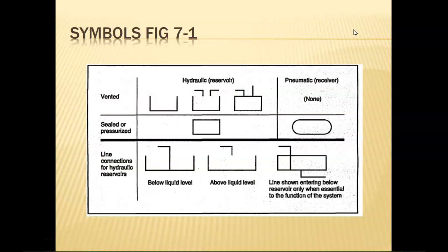Some different symbols. You have hydraulic reservoirs. These are ones that are vented versus a sealed or pressurized. Now, the different ways that they're showing you to collect the fluid with the pump. Anybody ever dealt with hydraulics? A couple of y'all? Where do you want your pump to sit? Do you want it to sit at the very bottom of the reservoir, at the very top of the reservoir, or somewhere kind of just barely above bottom? You want it above the bottom. Why? Well, how many of you have ever changed your oil?